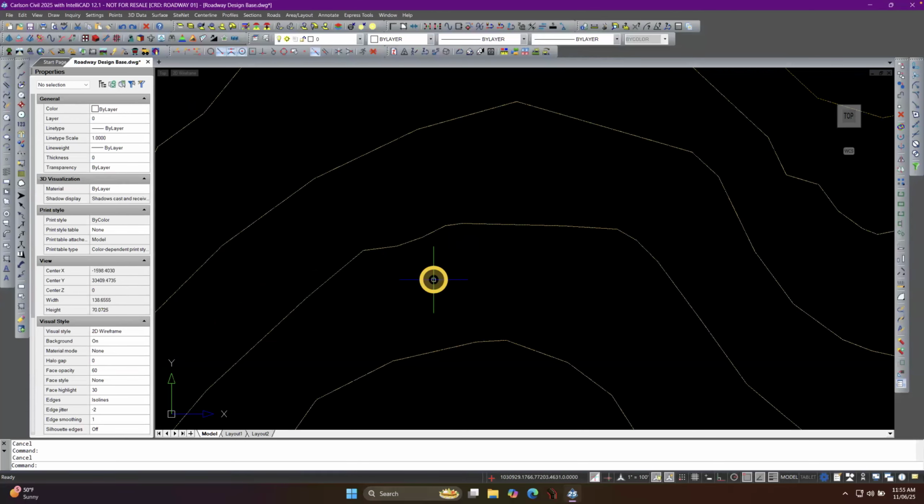Now you can also set that in your drawing template or set it before you do the command. And that's with a command called pline gen. And if we type that, it wants to know the new value. I'm going to turn it on.